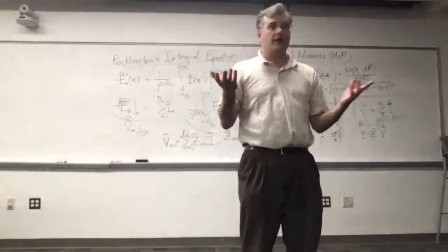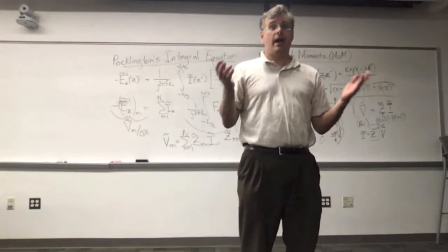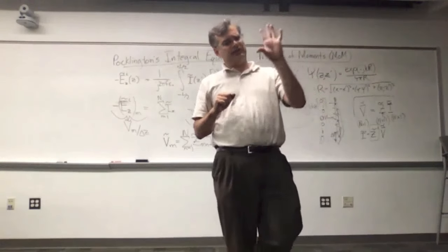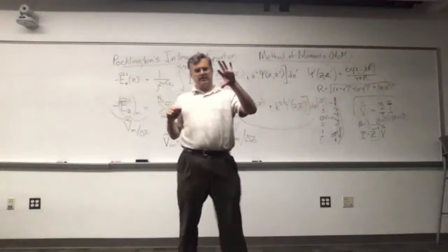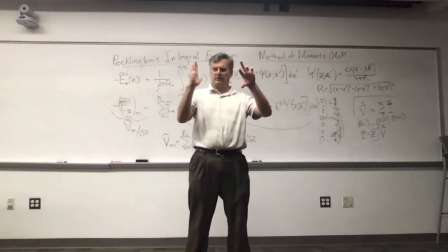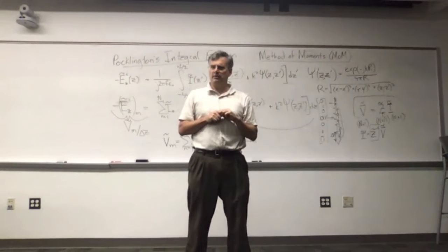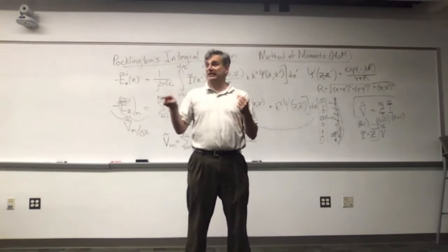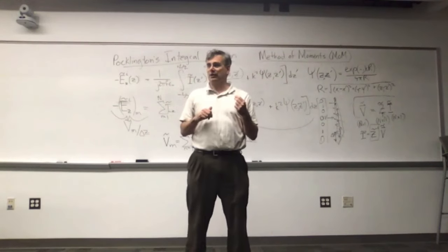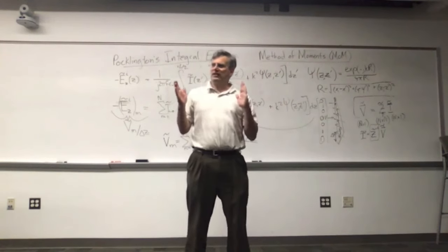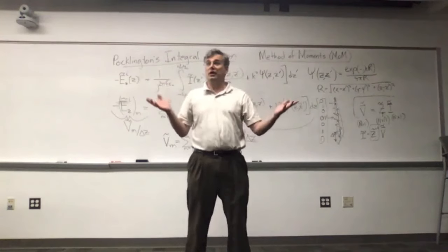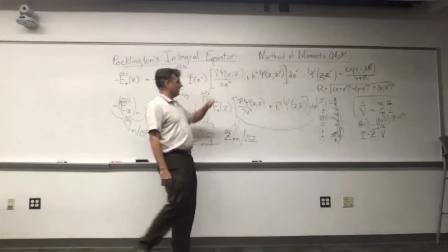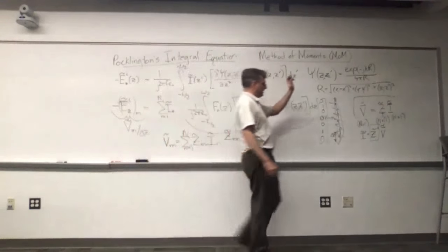But then along comes the Yagi-Uda array. And we know that there's going to be a sinusoidal standing current on the driver, because that's a dipole. We know something like that is going to be on the director and the reflector. But how do we figure out the phase? Is it a true sinusoidal hump? It won't be exactly a sinusoidal hump. What is the phase of one of those elements with respect to the other elements? We don't know. We don't have any basis for computing. The best thing to do is solve that numerically using this system.